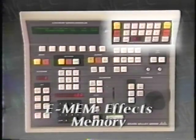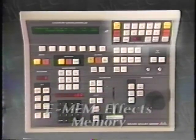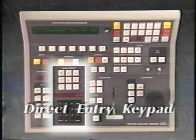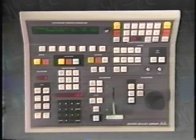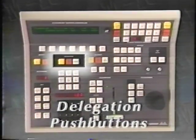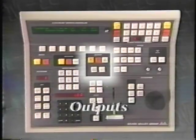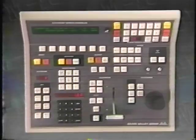sequences you've created can be stored and later recalled with a touch of a button, the direct entry keypad for directly entering numerical values for picture setup and manipulation, the delegation push buttons, which delegate the control panel to Channel 1, Channel 2, or global functions. Output controls the output of either Channel 1, Channel 2, or their combination. Make note that the second channel with the combiner is an option of the DPM-100.